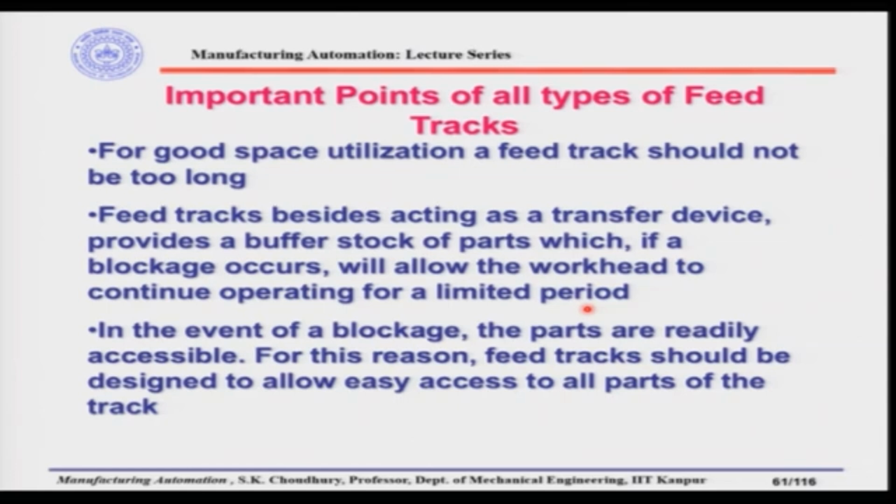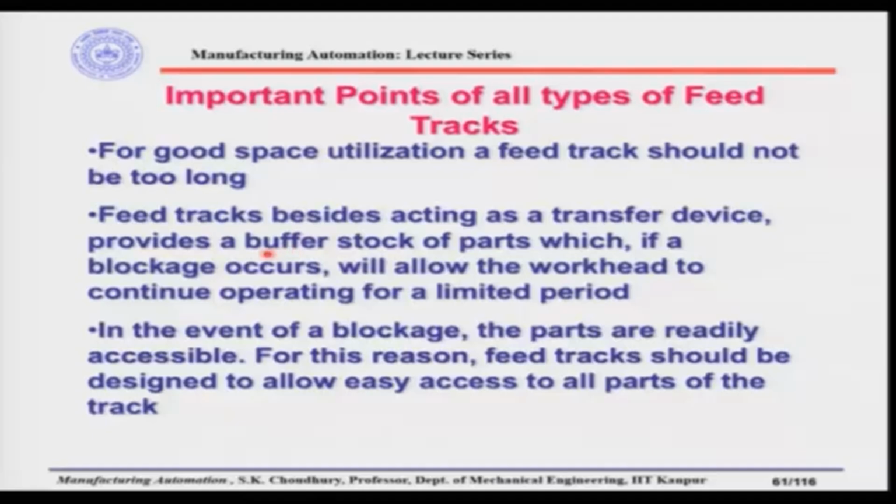Initially we said that it should not be too long, but it should be sufficiently long so that parts can be stacked as a buffer stock. Suppose the ball feeder stops, the assembly machine can still get the parts which are stacked inside the feed track. So, the feed track can work as a buffer stock, for a certain time, of course.